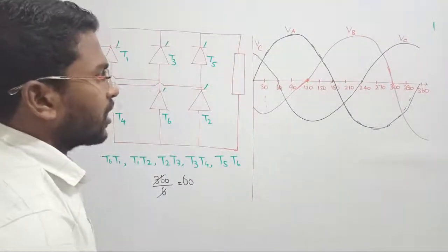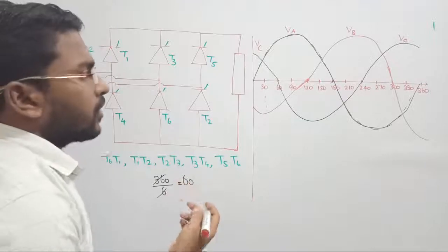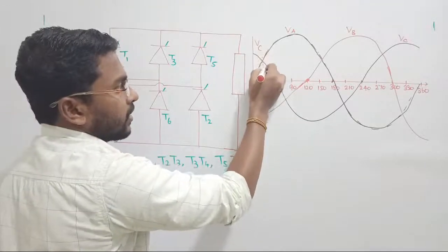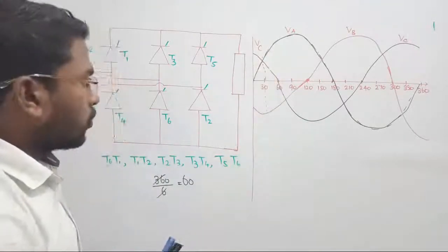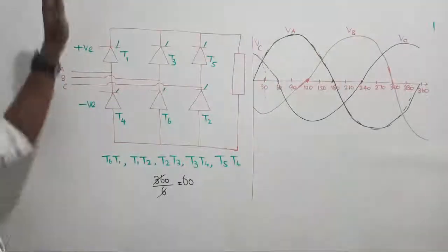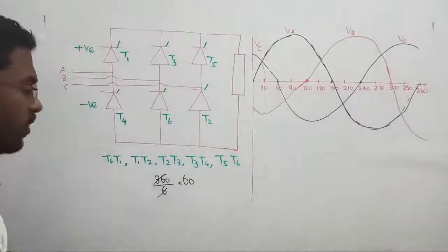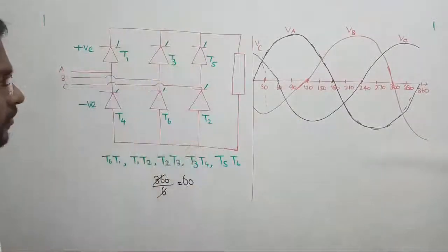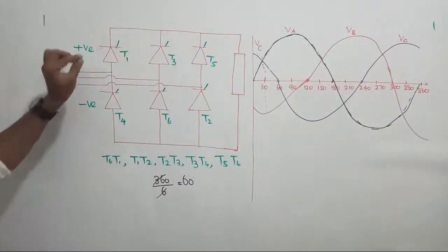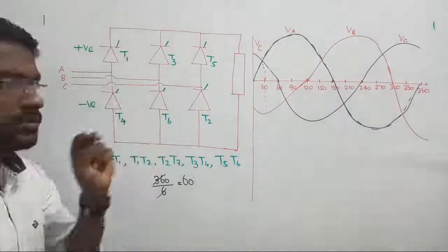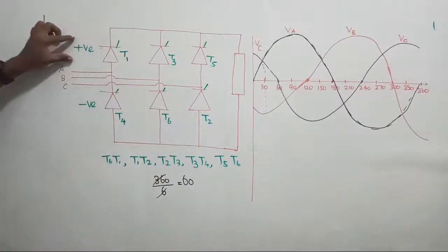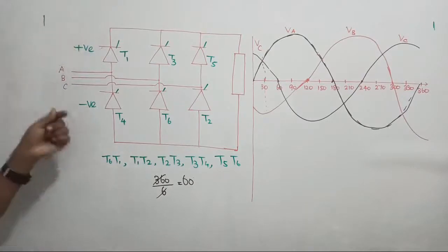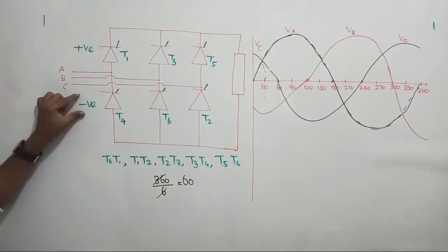Once again, now tell me what is the minimum period of the thyristor triggering angle? I said if you want to consider leg number 1. Getting back, listen here. Before understanding these things, take your fully, that is 3-phase full wave rectifier. In this case, in each and every leg, we have 2 switches. One switch will be turned on with the help of positive voltage, whereas while talking about switch 4, we are talking about negative voltage.